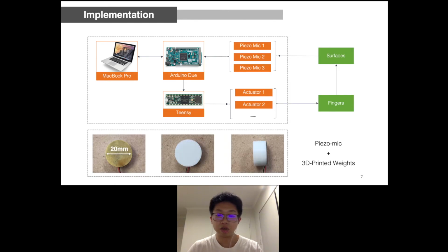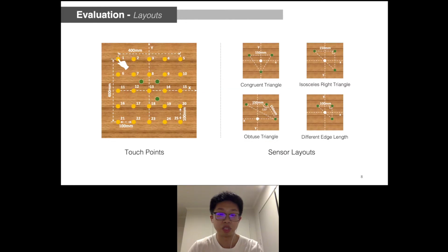Here is a detail of our customized microphones. It consists of a piezo which has a diameter of 20 mm and a 3D printed weight. The weight is to make sure the sensor contacts the surface well. And we also conducted several studies to evaluate the sensing capability.